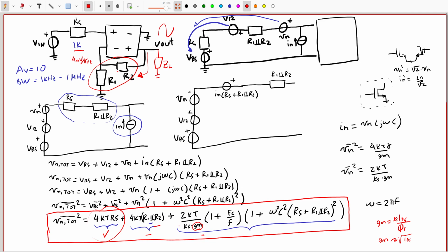we are not going to deteriorate the noise too much, and that we are just going to raise the noise floor 3 decibels. That means that 50% of the noise will come from the source, and 50% of the noise will come from the other components.